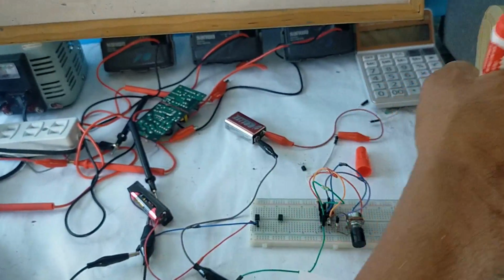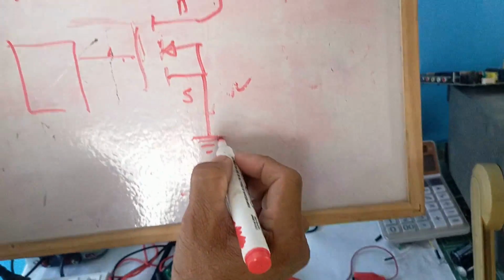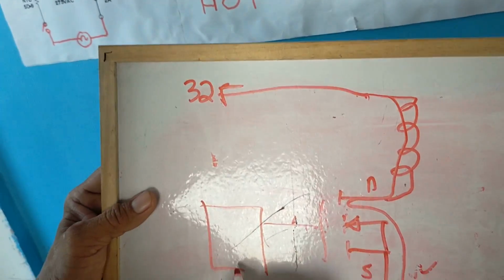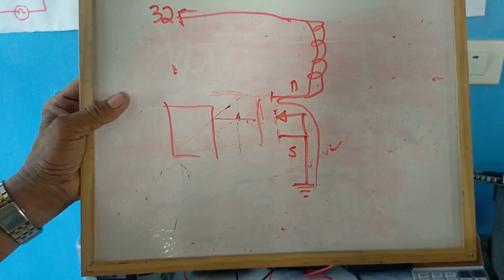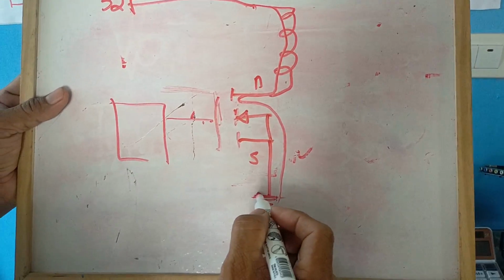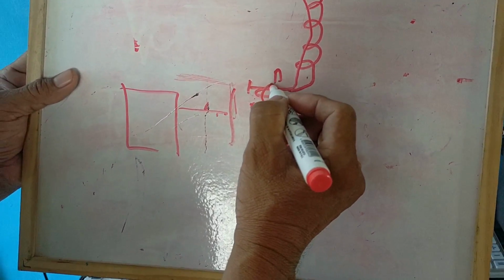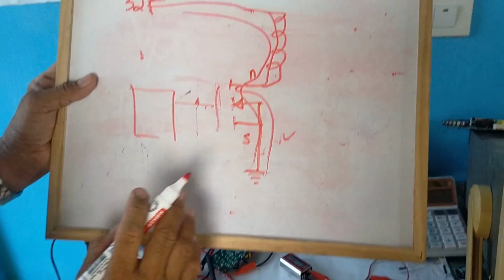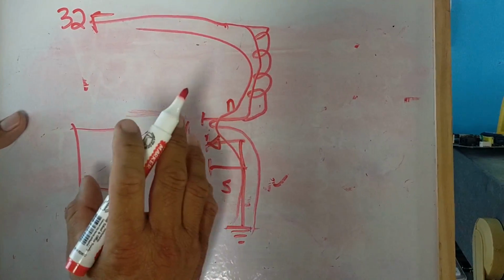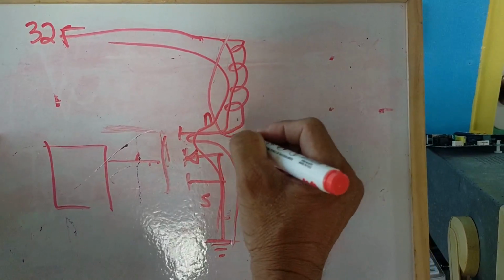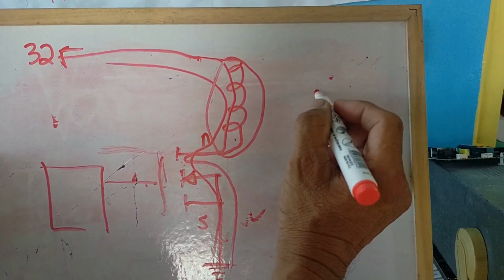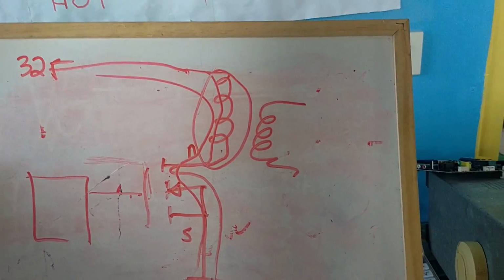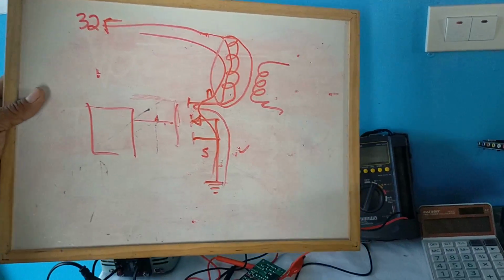When it is turned on, the transistor will conduct. So there is a flow of current here from source to drain. But anytime that it is dropped to zero, cut off, there is no flowing of current here. Zero. So that should be the action of the switching transistor. Turn on, turn off, turn on, turn off, turn on, in such a way that there is variation of the magnetic field here that provides voltage at the output. It is still AC. Okay? So it goes like that, class.